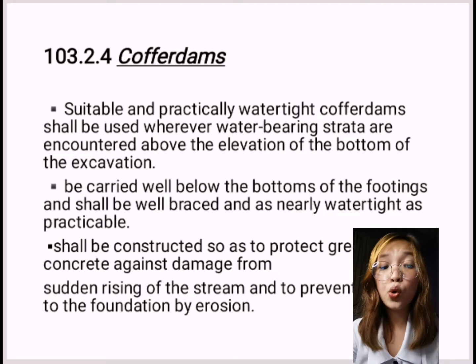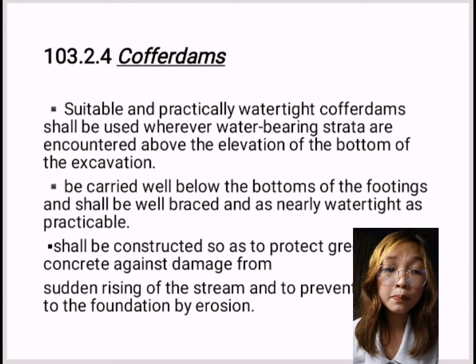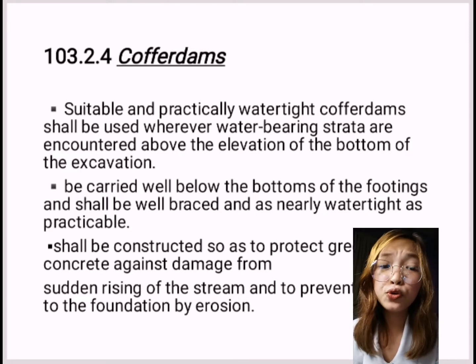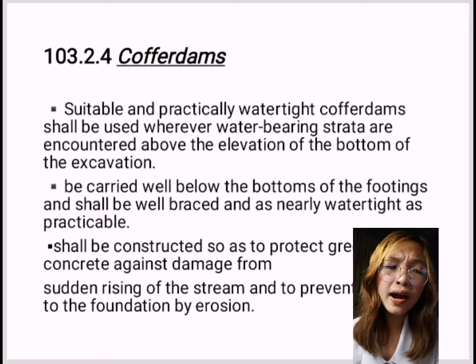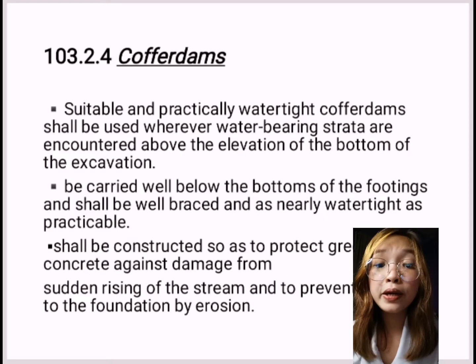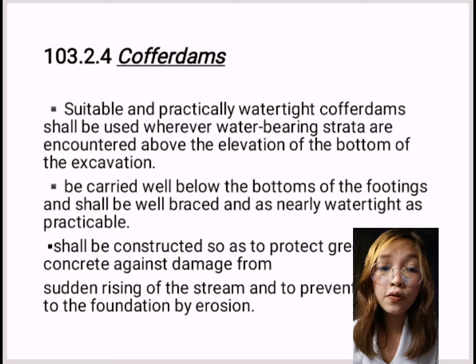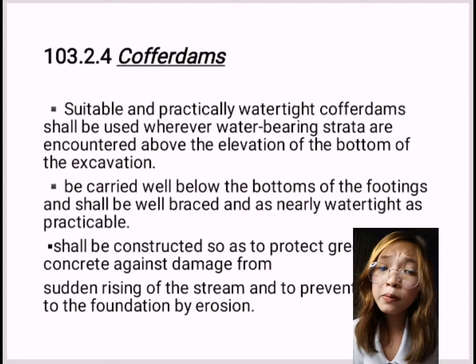So cofferdams or cribs for foundation construction shall in general be carried well below the bottom of the footings and shall be well braced and as nearly watertight as practicable. So in general, the interior dimensions of cofferdams shall be such as to give sufficient clearance for the construction of forms and the inspection of their exteriors, and to permit pumping